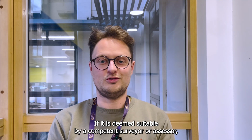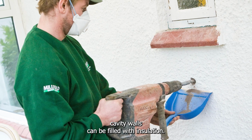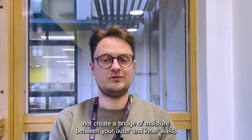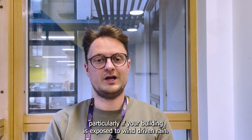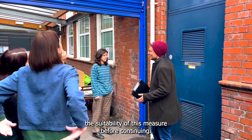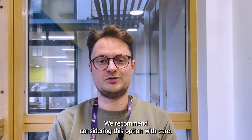If it is deemed suitable by a competent surveyor or assessor, cavity walls can be filled with insulation. You'll want to make sure that your insulation does not create a bridge of moisture between your outer and inner walls, particularly if your building is exposed to wind-driven rain. Not all cavity walls will be suitable for insulation, so it's important to ensure a surveyor fully understands the suitability of this measure before continuing. We recommend considering this option with care.